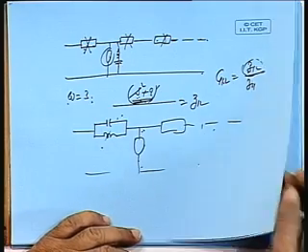Okay. So, this is the technique of two port synthesis. When you are given the transmission zeros, you convert them into poles and then try to realize a pole. Any 0 can be realized in terms of a pole, is it not? How do you do that? Suppose you are given Z12. How do you remove that? How do I remove a pole, a 0? You take inverse of that function. If it is in the admittance form, then you convert it into impedance and then make a partial fraction corresponding to that pole, remove that. Okay.